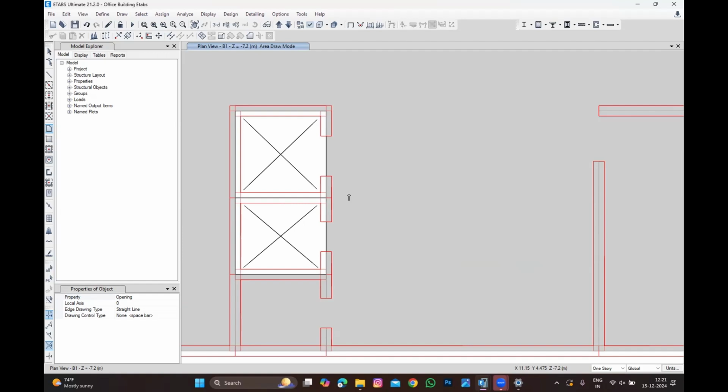Even if it is not connected, the waist slab is touching the wall, right? If it bends, it will never bend the whole wall. It will only bend between the waist supports. Practically, there are two kinds of movement: in plane and out of plane. The out-of-plane is about stiffness. The in-plane is the one connected to the slabs.